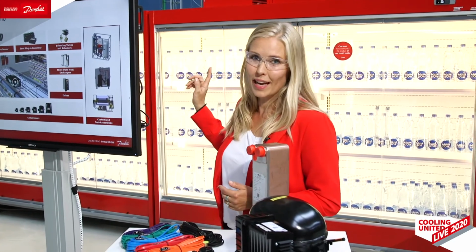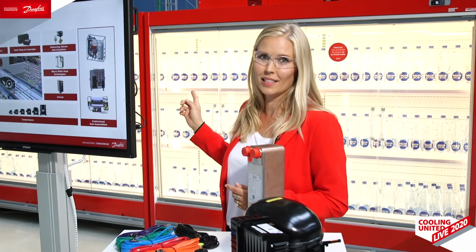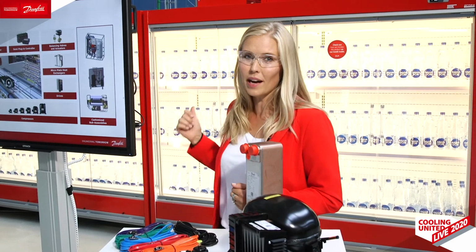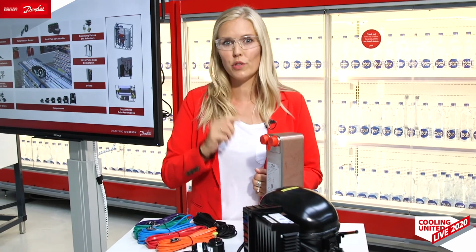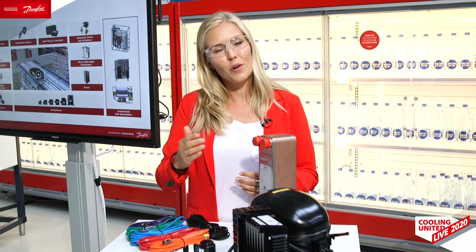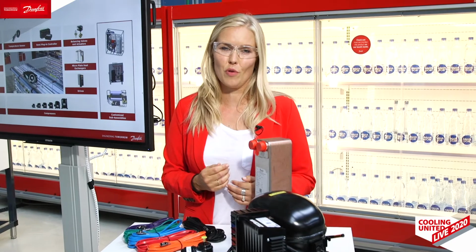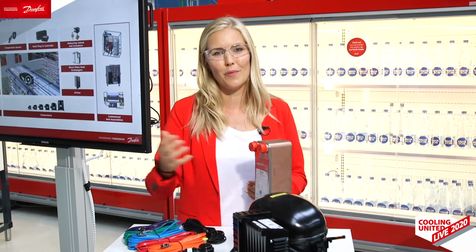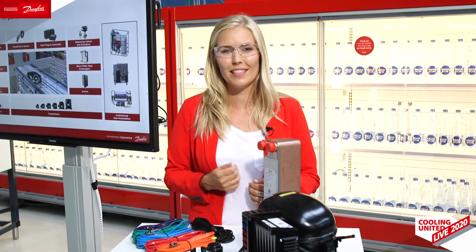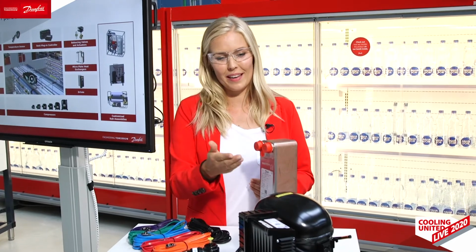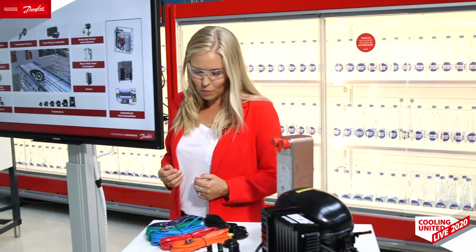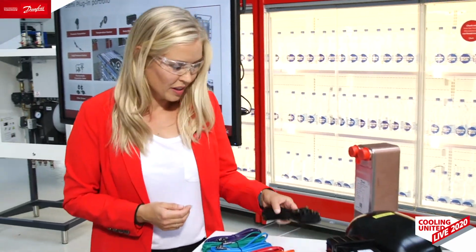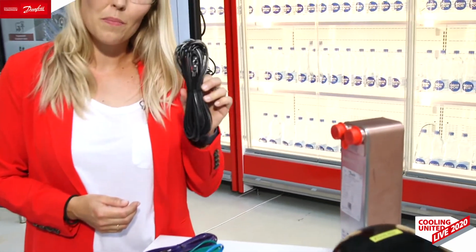And in fact, one of the cases we have here behind us is a 2.5 meter case that we are running with one of these compressors, variable speed, in one refrigerant circuit, going a little bit above the 150 gram refrigerant limit, so referring to the IEC standard that Stefan was mentioning before, but we are using these compressors for this. Another component is the temperature sensor, and in the past we had the black one.